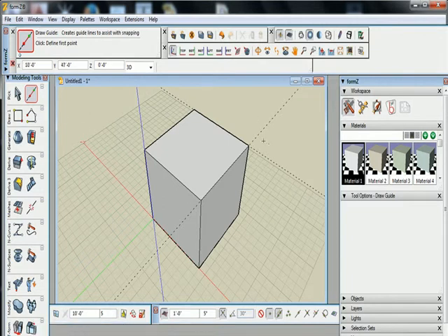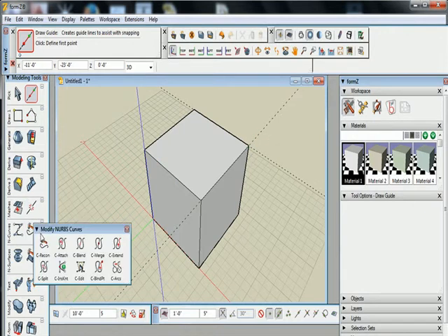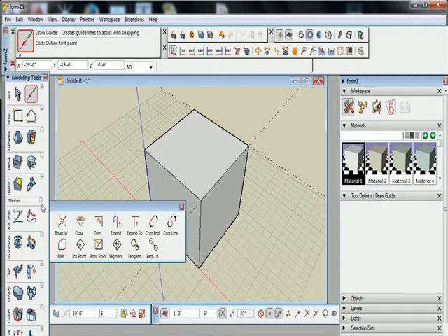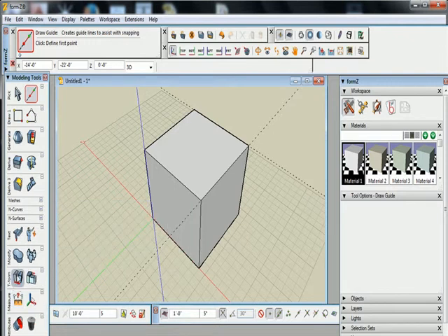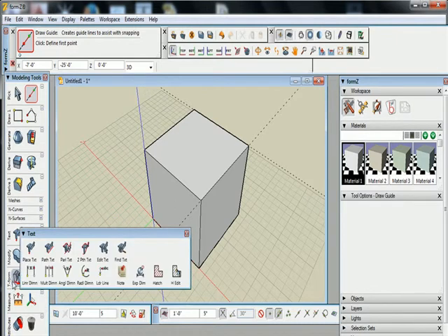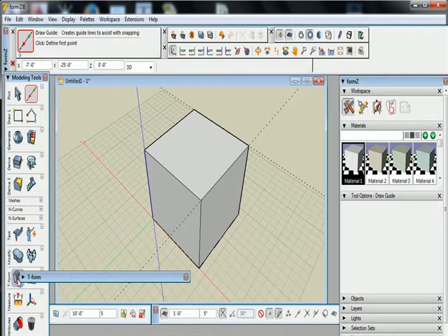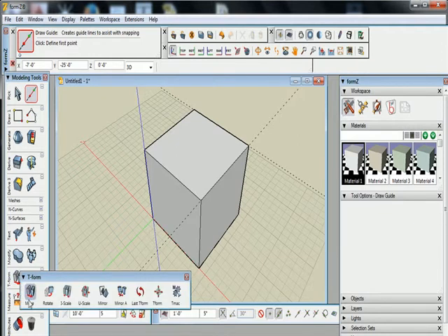Once you have the guideline set, we're going to move this guideline. There is a move tool. Let me close some of these tools that I know I'm not using so that we can see some of the bottom parts that we do need to get to. In the palette, towards the bottom, it says T-form. T-form is transform. If we open that up, you see the first tool in there is move, rotate, scale, U scale, mirror, and transform and all that stuff.